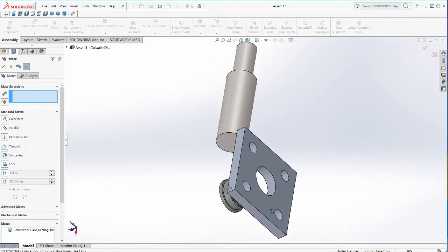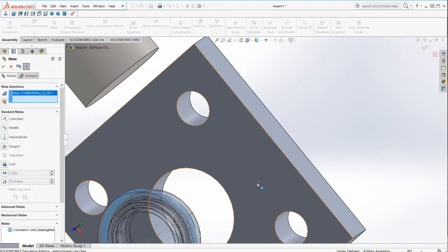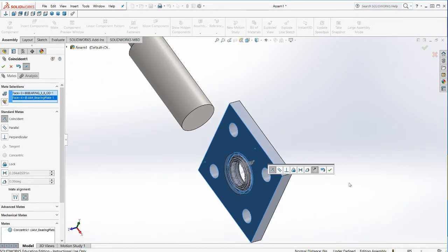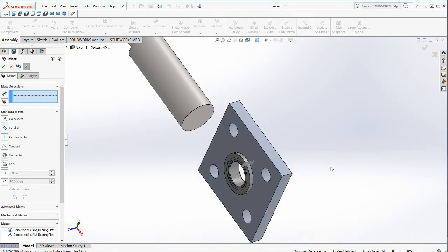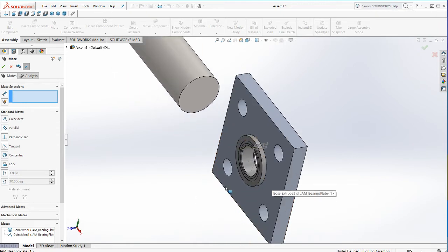So I'm going to grab the back of this flange and put it right onto the face of the plate. Because when you press fit a bearing into a plate, you're going to apply pressure on the bearing using a drill, well, no, not a drill press. We have a press in the shop. And you're going to press this bearing into this plate, and it's going to stop when it gets far enough, right? So that's physically why we tend to use flanged bearings.